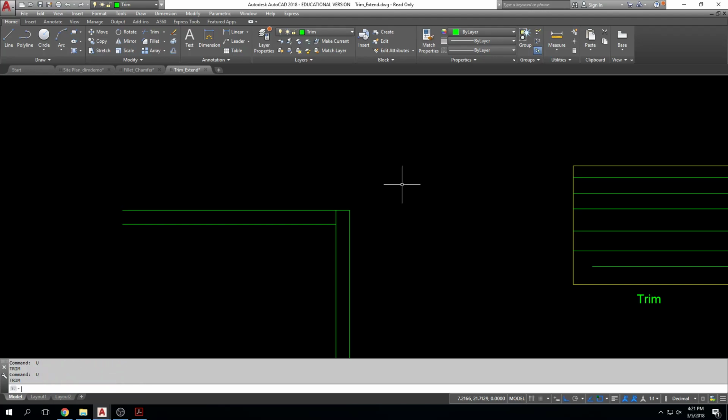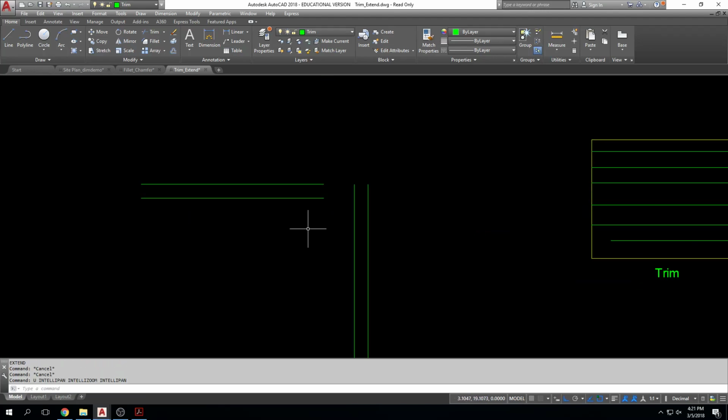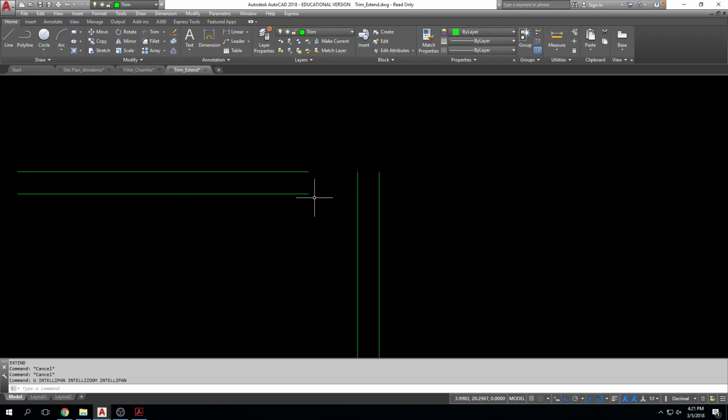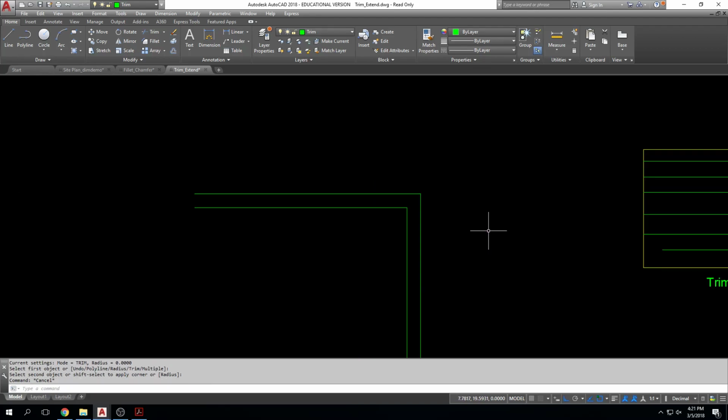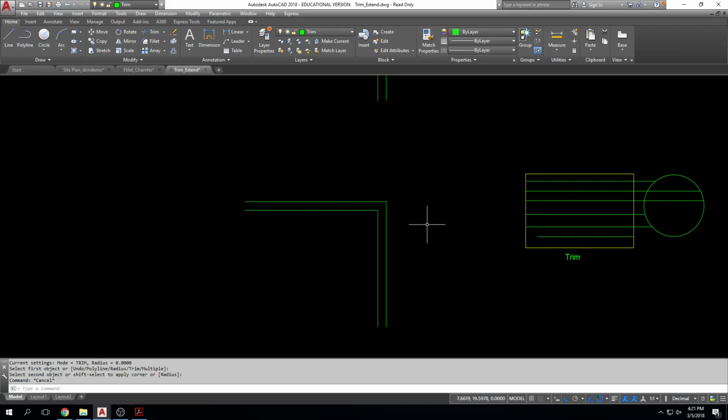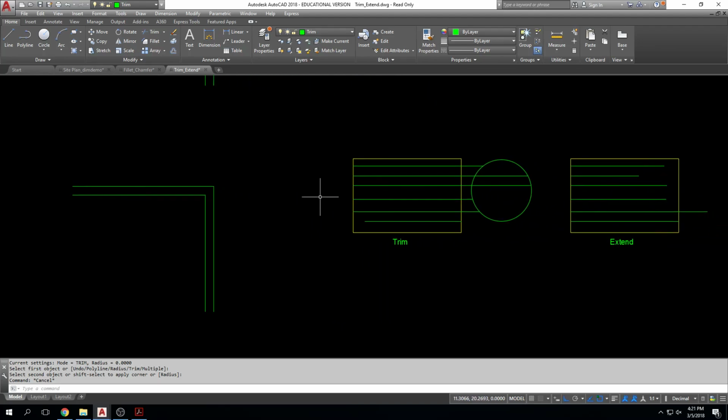And you're likely going to now see why, oops, undo, why I kind of like fillet, because it's like trim and extend in one command. I can extend, extend, extend, trim, trim, or I could F for fillet, enter, R for radius, 0, and I can click, click, enter, click, click. It's kind of a much cleaner method of squaring things off. So fillet is kind of trim and extend all in one piece. But trim, TR, enter, enter, will allow you to trim pieces off, click.